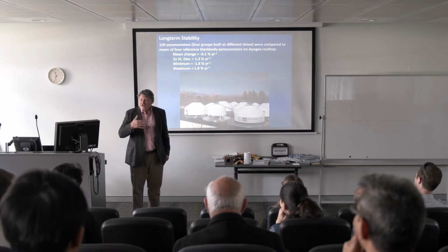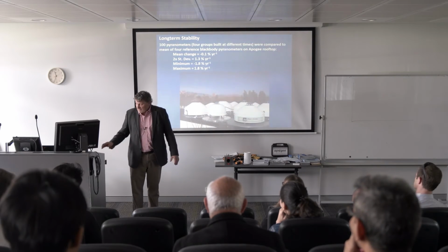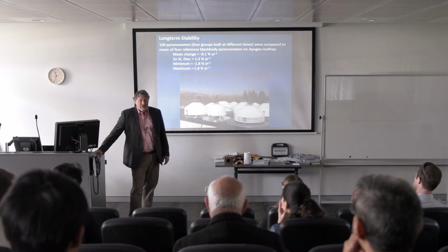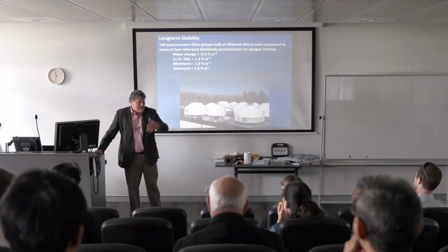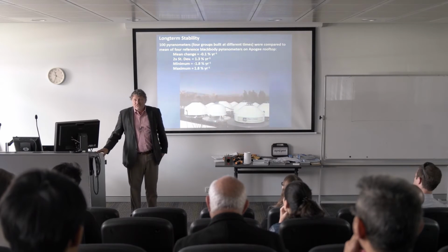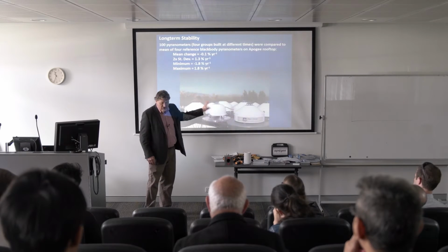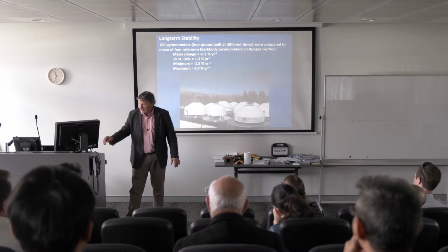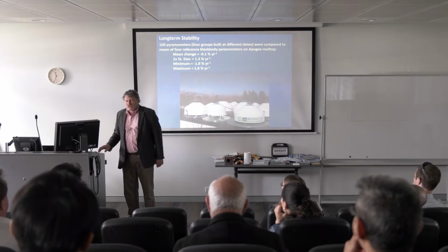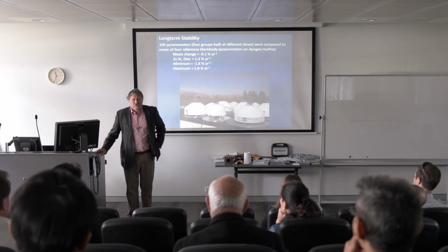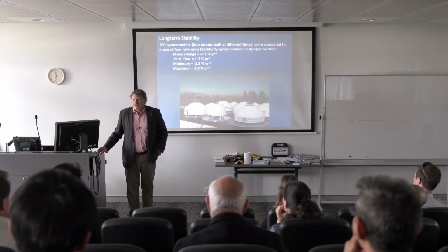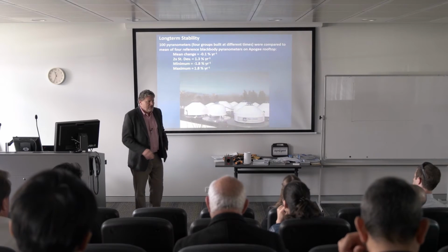It's an interesting change in the development of sensors. They felt like taking that out helped people make better measurements than leaving it in and making them go and change the desiccant in the sensor. Because of that, we've worked hard. We pot our sensors solid, so in the pyranometers there's no airspace. So moisture can't get in and cause problems with the measurement.